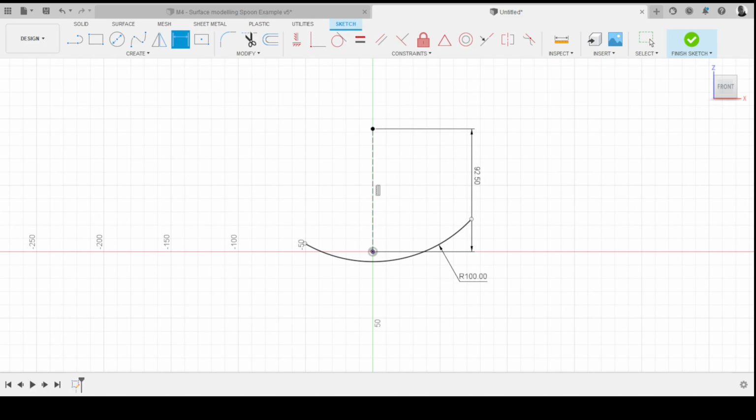Can you put constraints on them? Yeah. What kind of constraint do you think we might put? Equal? No. Coincident? No. Symmetrical. Yes. It's a pretty obvious trick question, really. You've got a symmetry constraint, which is a really useful one to know about. The way to do it is quite descriptive: you click on the two ends, and then the midpoint you want to be symmetry around. So I click on one end, the other end, and then this center line. And it will make it symmetrical.